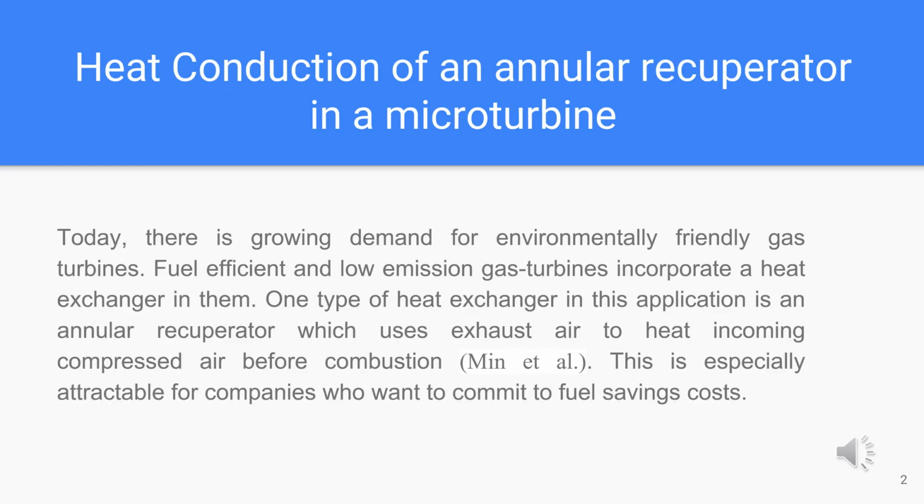Today, there is growing demand for environmentally friendly gas turbines. Fuel efficient and low emission gas turbines incorporate a heat exchanger in them. One type of heat exchanger in this application is an annular recuperator, which uses exhaust air to heat incoming compressed air before combustion. This is especially attractive for companies who want to commit to fuel saving costs.